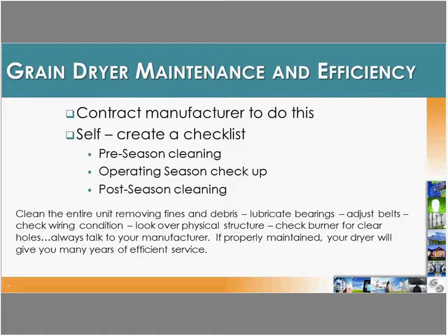If you are doing it yourself, and you're able to stay on top of that, do the pre-season cleaning, during-operation cleaning, and a post-season cleaning. Clean the entire unit, removing all the fines and debris. Make sure you're lubricating the bearings, checking the belts for tightness or adjustment, and checking the wiring condition.